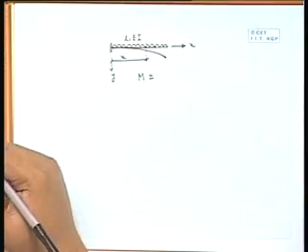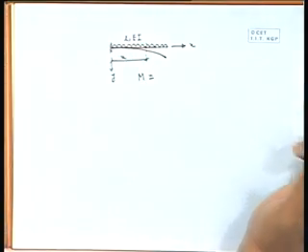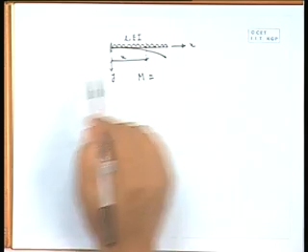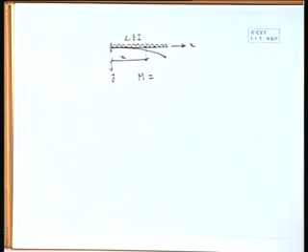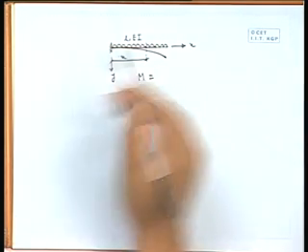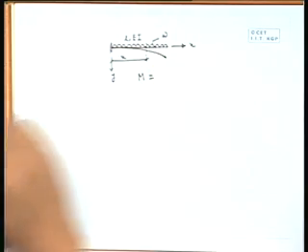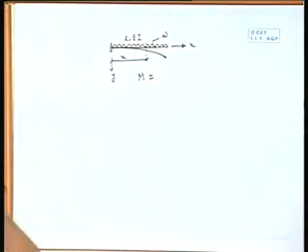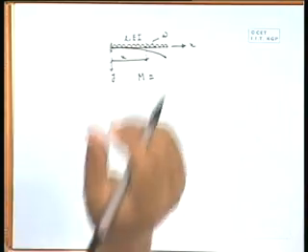Right. Now, at any distance x, so there is one cross section, what will be the expression of bending moment? We can calculate from the right end because that is a free end, it is easier to calculate. So beyond that section on the right side, the loading is, first of all, the length of that will be L minus x, and the loading is say W or omega, that is the intensity of the distributed load, the load per unit length.